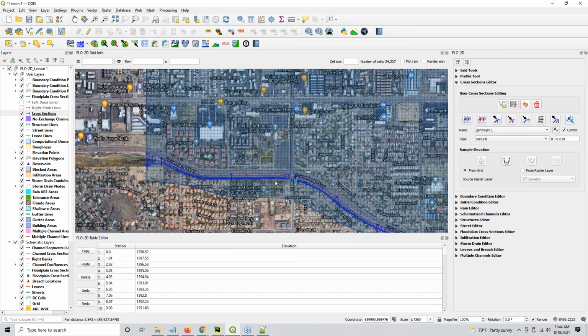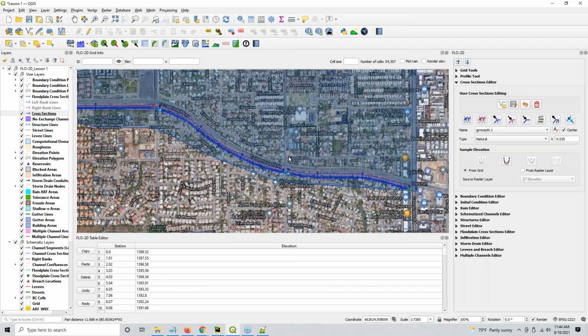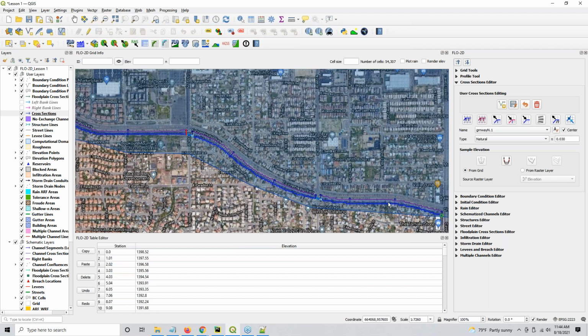And again, I'm sorry if this is kind of overly complicated because you wouldn't typically see this mixed geometry. Normally, I would just cut the cross-section data for these 3 channels, and I would just cut it straight as a natural channel. I wouldn't mess with the 3 different types of channels, but because I wanted to show you how to do it, video 1 shows you how to start setting it up. Video 2 shows you how to finish it off by adding the hydraulic structures and the inflow nodes. And video 3 is kind of an overview of what we did.